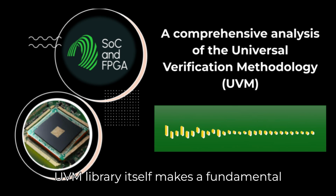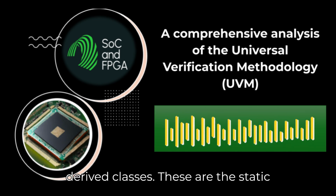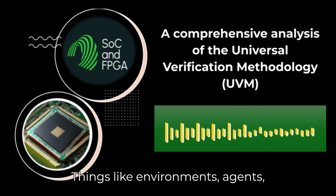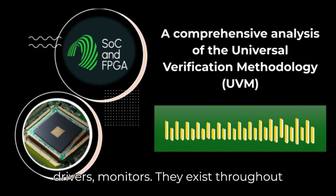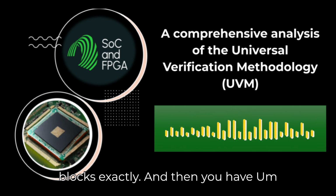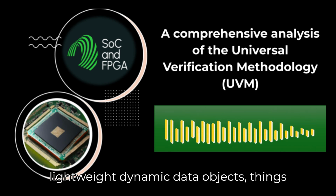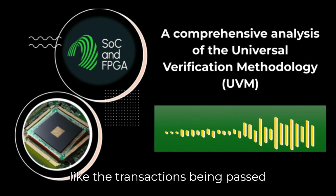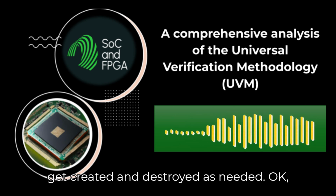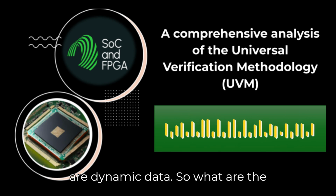Right. The UVM library itself makes a fundamental distinction. You have your UVM component-derived classes. These are the static structural parts of your test bench. Things like environments, agents, drivers, monitors. They exist throughout the simulation. The persistent building blocks. Exactly. And then you have object-derived classes. These are more lightweight, dynamic data objects. Things like the transactions being passed around or configuration objects. They get created and destroyed as needed. Okay, components are static structure, objects are dynamic data.